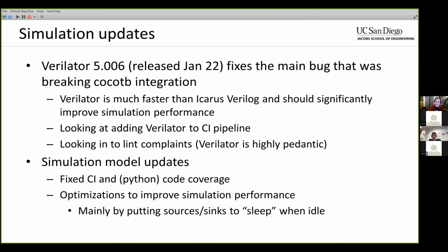So basically, instead of always waiting for the clock edge event, if there's no data currently being sent, we'll await something being enqueued, or we'll await t-valid going high, something like that. Save a few CPU cycles and make things a little bit more efficient.